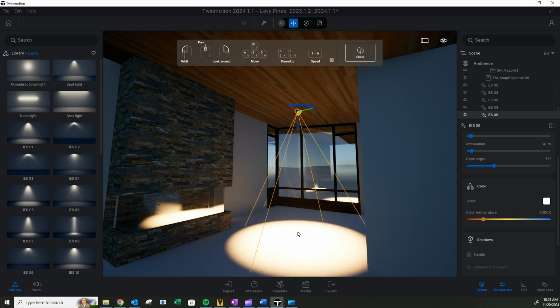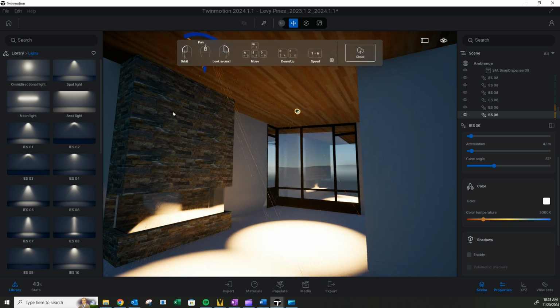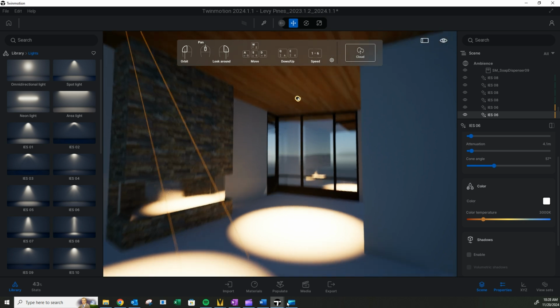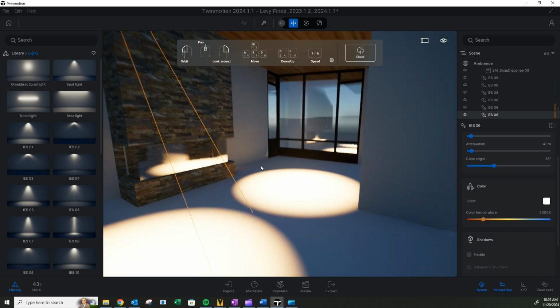And that's why most lighting manufacturers have a spacing criteria where it says SC 0.8 or SC 1.2. You take that and multiply it by the ceiling height, and that tells you how far you can space these apart without getting any of that darkness, that light gap.